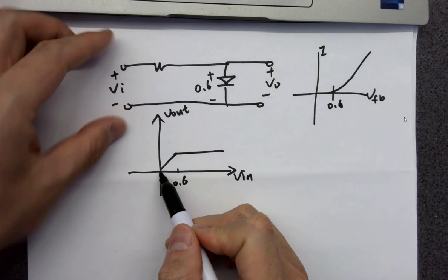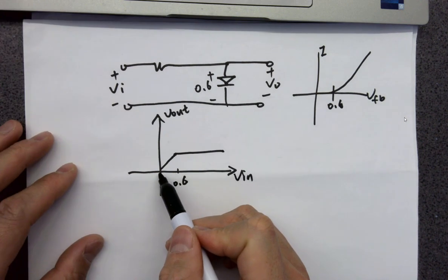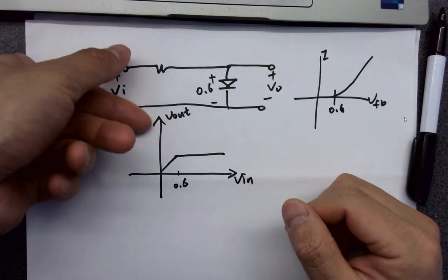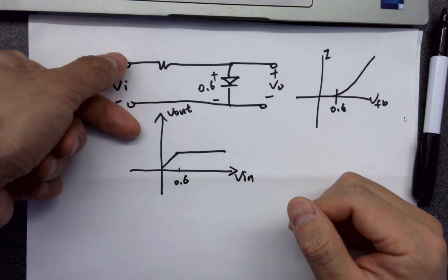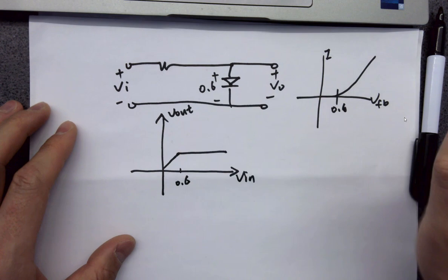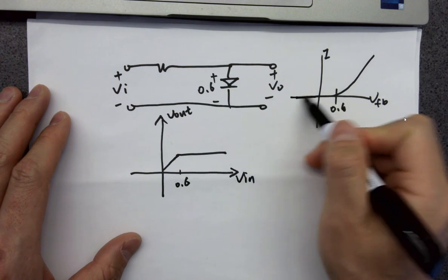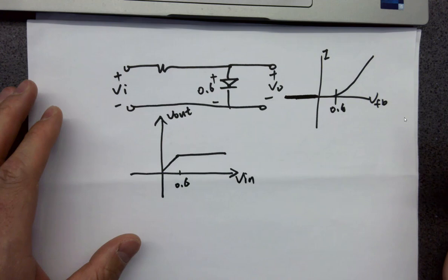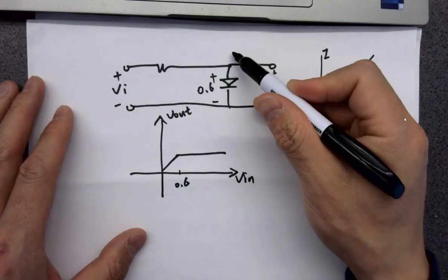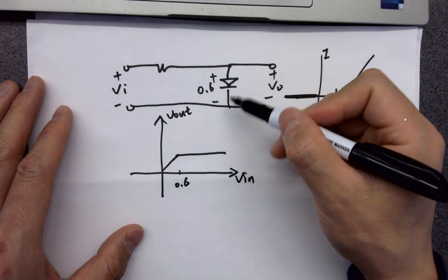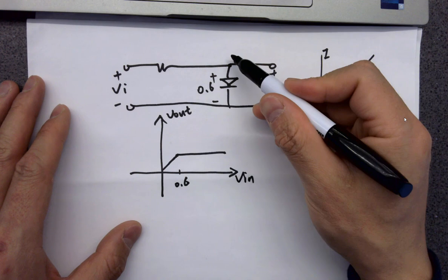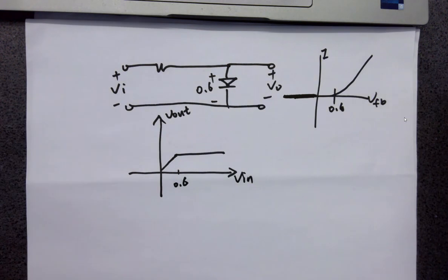What about reverse biasing? Whenever the voltage becomes negative, which means this voltage is negative, or you can say this voltage is positive, it's reverse biasing this diode, and you are not getting current at all. Ideally, at a certain point, it's going to penetrate the diode. If you reverse bias it and the voltage is larger than the limit, it's going to break down and you cannot recover it. That's the regular diode.